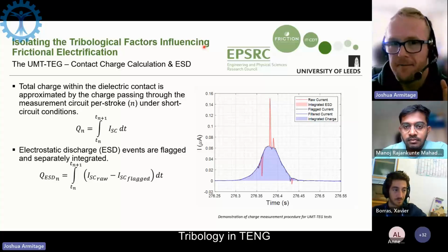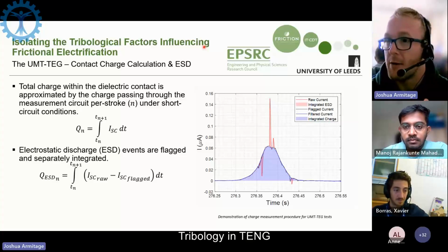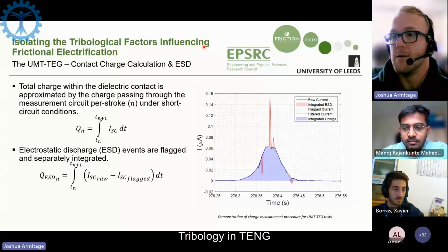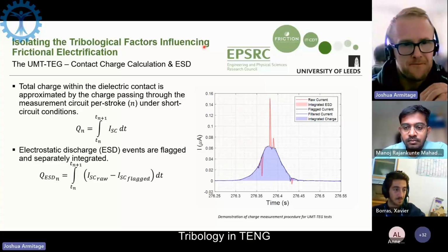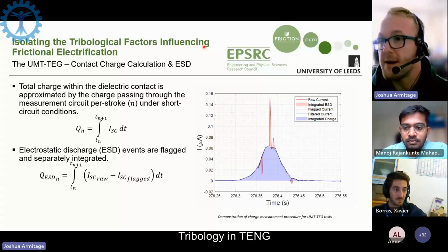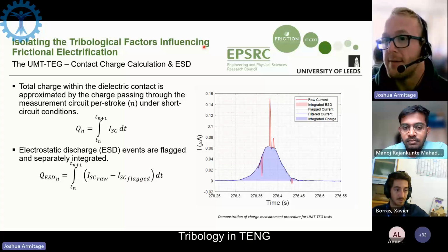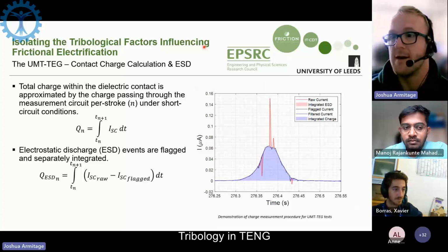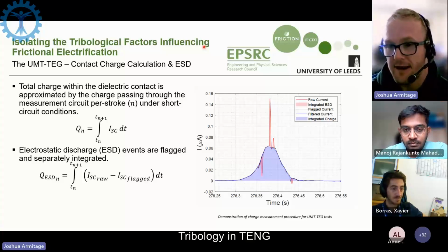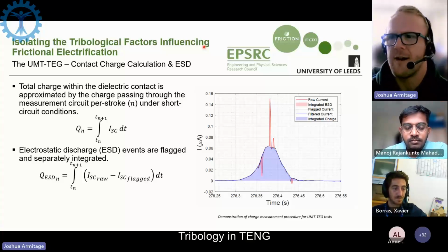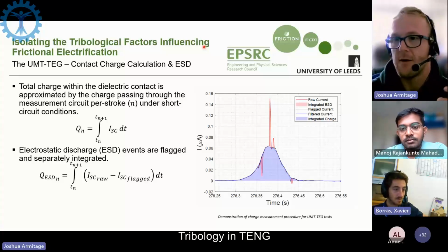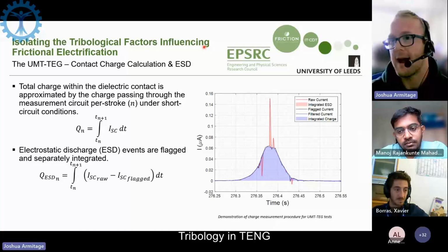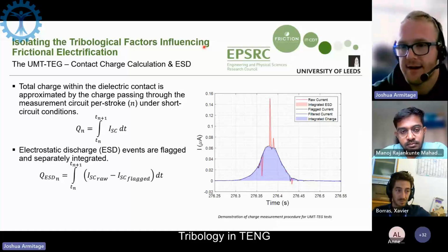Unfortunately, I'm currently modifying our contact model to calculate the magnitude of this adhesion for our surfaces, but I believe there actually has been a paper that's been investigating whether the amount of charge within a contact actually enhances friction. And so far, I think the general consensus is the more charge you have, the greater this Coulomb adhesion, therefore the higher the frictional resistance we get in the sliding contacts.